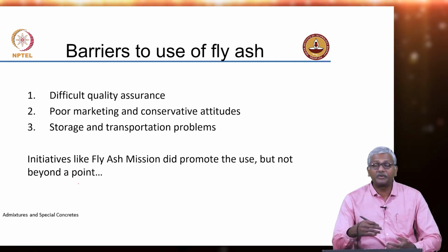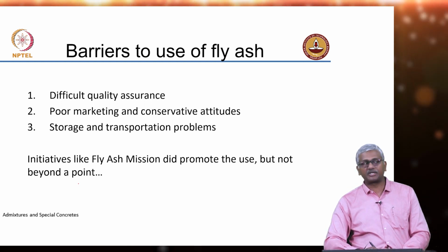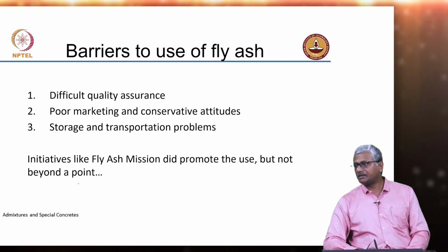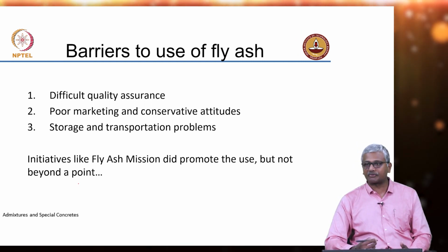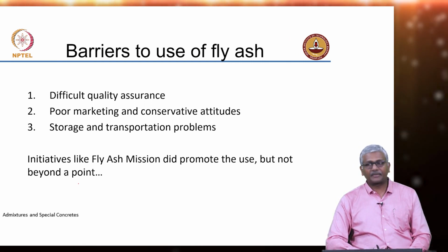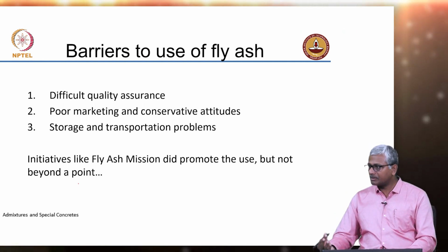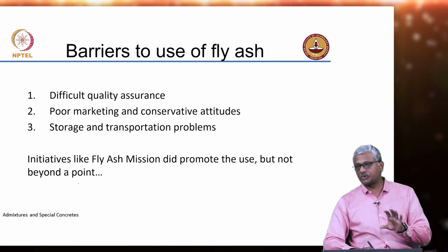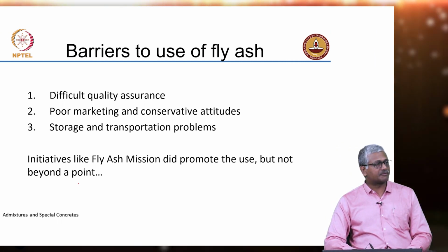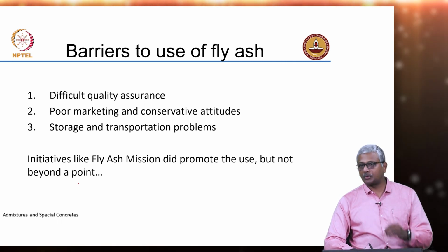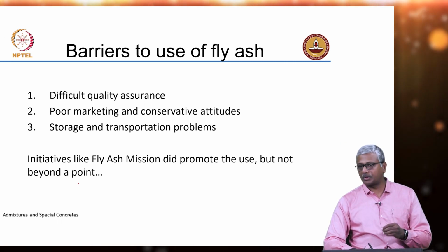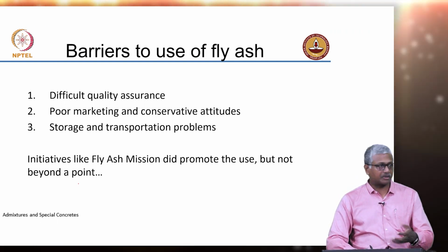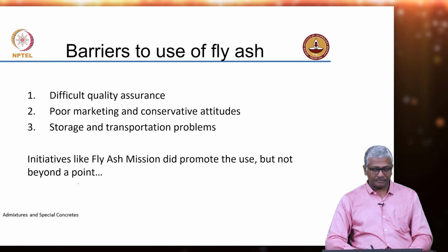Now, why? Because these precast pre-stressed members are subjected to early strength, they require early strength gain in such systems. They think that use of fly ash will spoil that, but if you look at data related to heat curing with fly ash, it shows that with fly ash you can still get sufficient strength development when it is heat cured. Fly ash responds quite nicely to heat curing, and because of such things there is no need to actually restrict the usage of fly ash. In fact, it may bring you long term durability benefits.